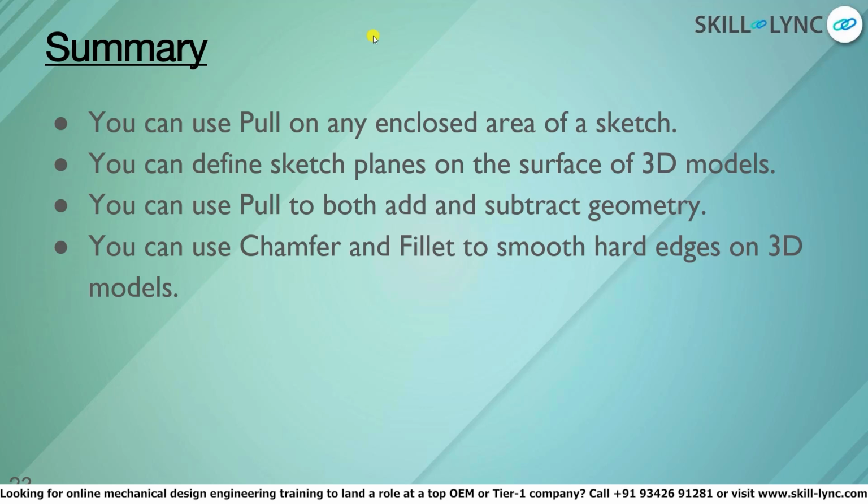You can use the pull tool both to add to 3D geometry or subtract from 3D geometry. You can use the chamfer tool and the fillet tool to smooth or remove hard edges of your 3D models.